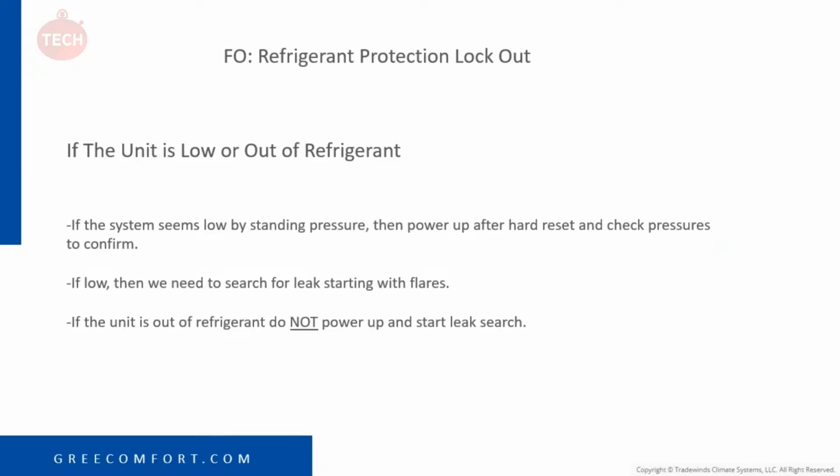And it also depends on set point. If that unit is set for 4 degrees or more than the indoor temperature, the unit is going to ramp up higher to achieve set point. So it all depends on set point, load conditions, indoor and outdoor temperatures as to your running pressure.